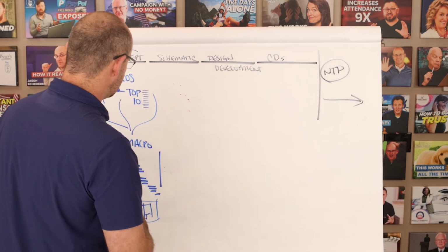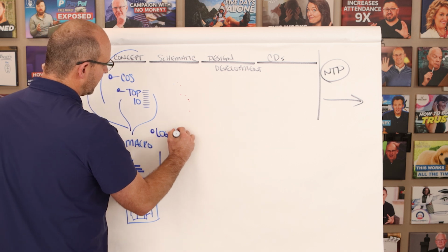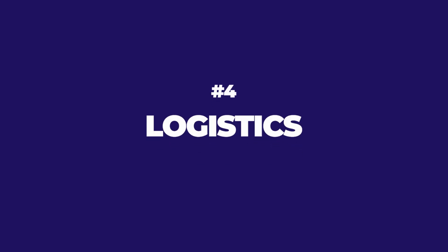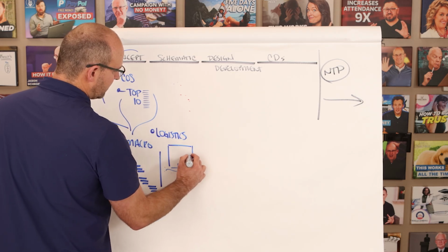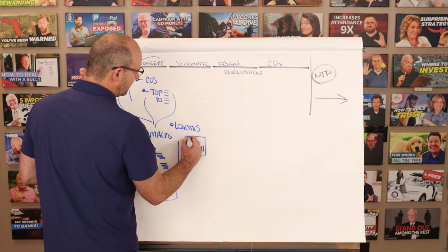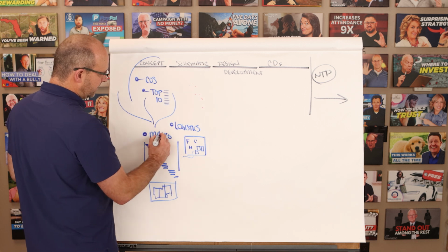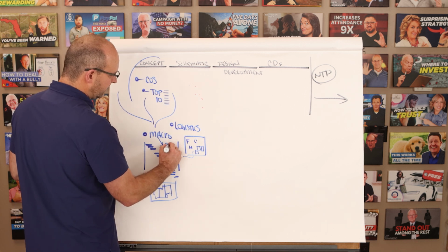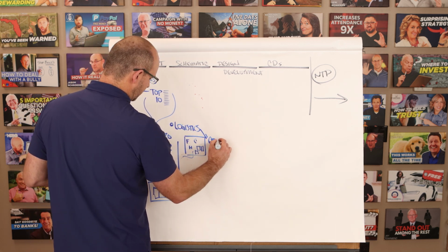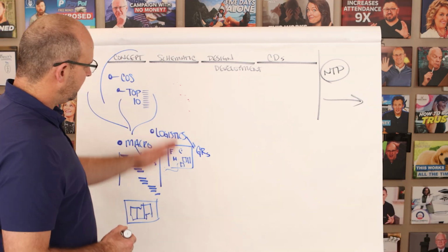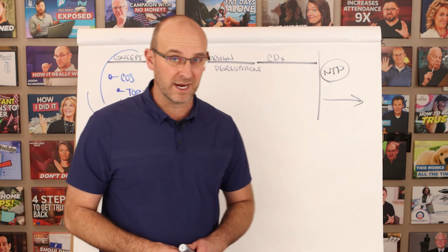In addition to your macro level Takt plan, you will want to quickly identify what your plan is when it comes to logistics, right? So your logistics plan is going to show the entry, the trailer, the parking lot, the laydown areas. Do you have a crane? Do you have a forklift? Do you have a hoist, right? This is going to help you with all of your indirects because your macro level Takt plan helped you identify your GCs, and your logistics plan helps you identify your general requirements, your GRs. So early on, you'll want to make sure that you have your logistics plan and that everybody can see it and that you know you can support your overall macro level Takt plan.